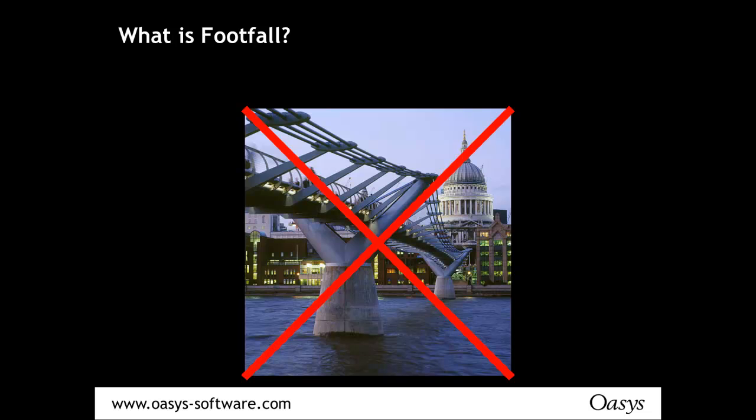Whereas with vertical footfall vibrations, you can walk out of step with the vibrations, which means achieving resonance is more accidental, and certainly you can't get large crowds locking step unless they're marching or in time with music and so on. Now, if you do want to know more about the horizontal footfall, there's a nice Structural Engineer paper on that, which we might be able to get you a copy of if you haven't got access already.